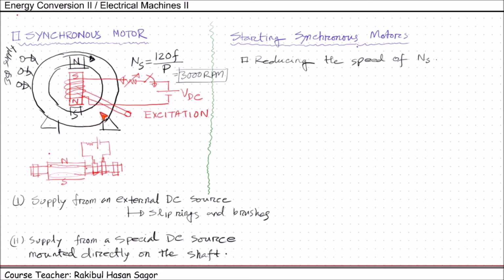Another method is that we can use an external prime mover to accelerate the synchronous motor up to synchronous speed.